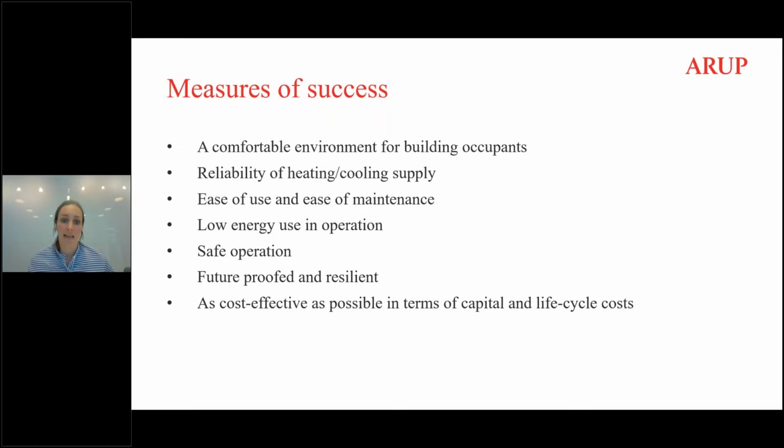And so some of these things can have some contradictions, and you might need to make some trade-offs or compromises. For example, it can be commonly thought that installing a heat pump is always a good thing because they're much more efficient. However, the embodied carbon impact of a heat pump is not insignificant. And so where possible, the installed capacity of your heat pump should be reduced, and perhaps you can use thermal storage, or in some cases direct electric, in order to reduce the installed capacity, maybe at the expense of operational carbon, but with an overall embodied carbon and whole life carbon positive outcome.